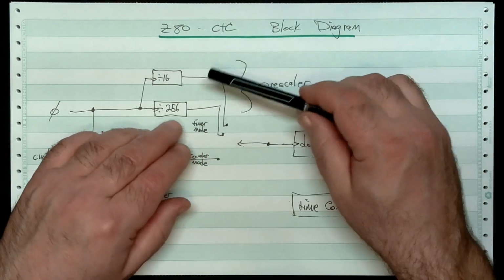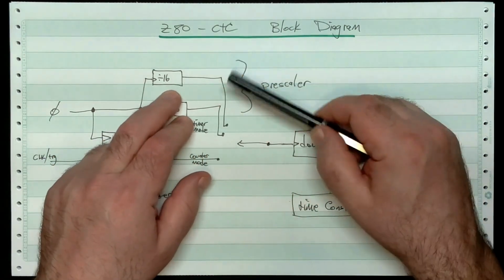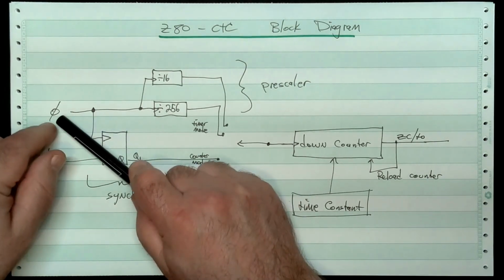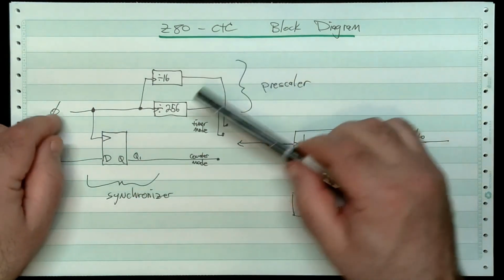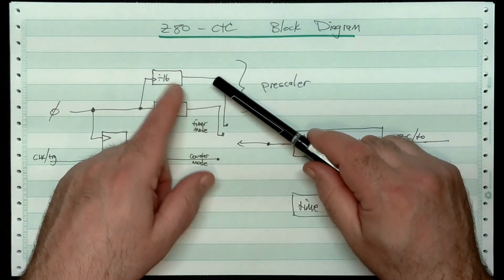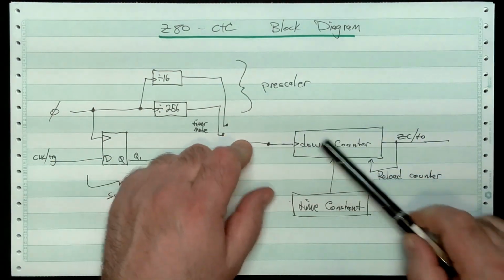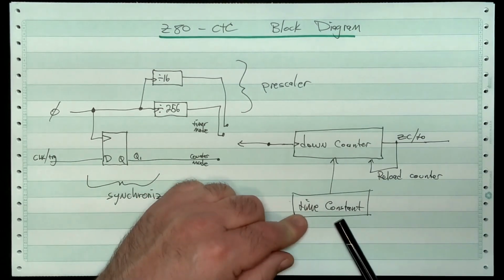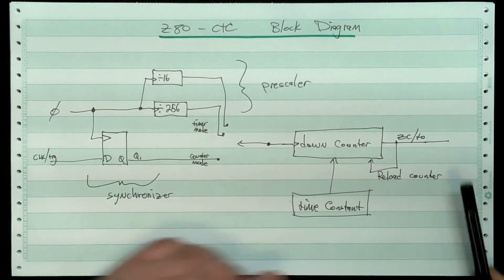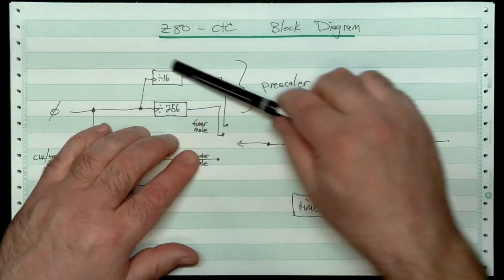So, if you choose divide by 16, what you're then doing is you're just simply taking the system clock, which is usually referred to as phi, or an italicized phi symbol, I guess, and running 1/16th of that in here, dividing it by some additional value, and generating your output over there, okay? So that's what it means to be running in timer mode.